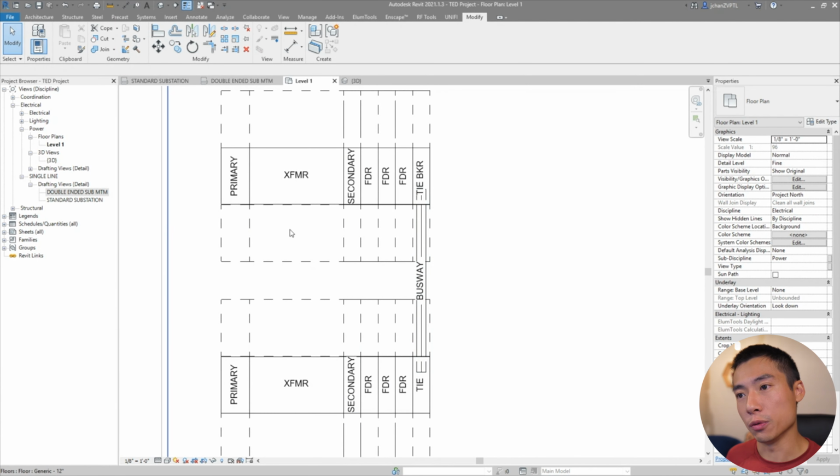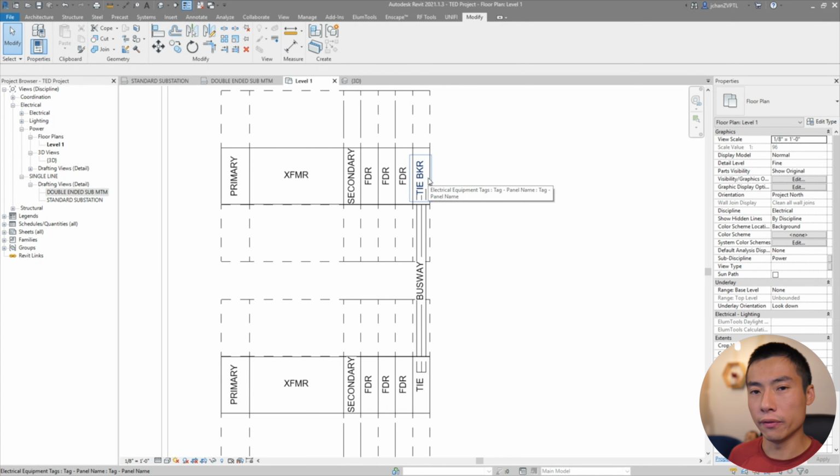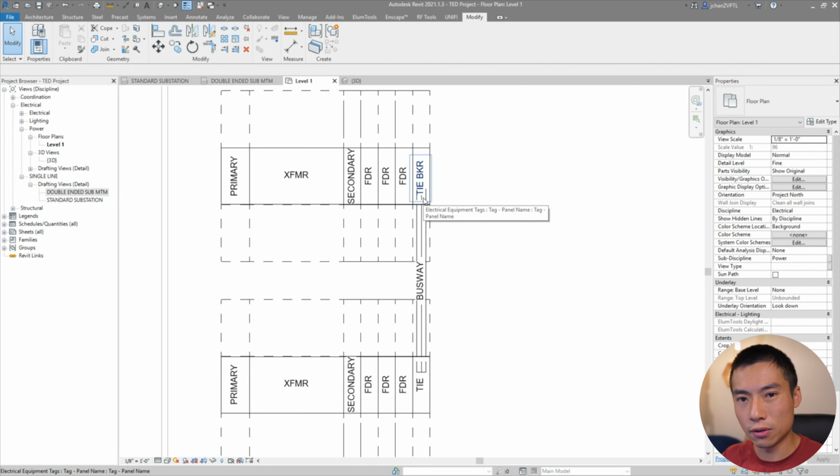So in this arrangement, the substations will be facing each other. So this is the front side, this is the front side, and usually just one of the tiebreakers is the one that switches, and the other one is just lugs. Like you have busway that just ties into the bus of the substation. Sometimes you can have 2 breakers and one just stays closed the whole time, and the other one is the automatic one that switches.